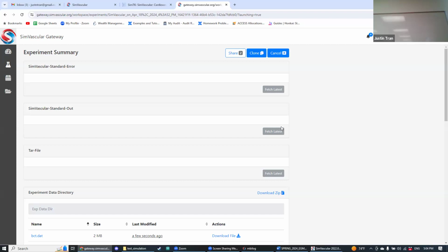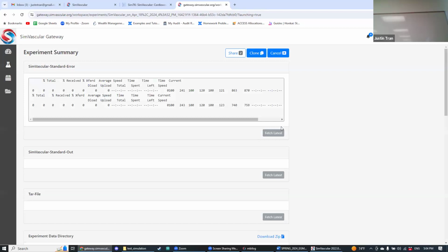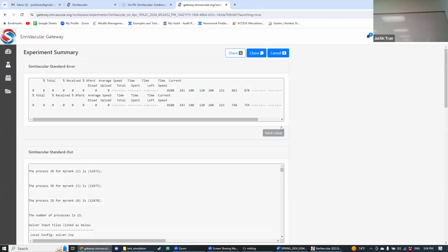Another thing that you can do, even though eventually you're going to have to do it for the full model, is that usually it's one or two vessels that are causing it to fail. And so you can create test models. You just swap a few vessels and try to mesh that, and that's usually the most successful. Then usually you'll find one or two vessels where it's like, that's the vessel that's causing it. It does take a while, but sometimes that's the option.